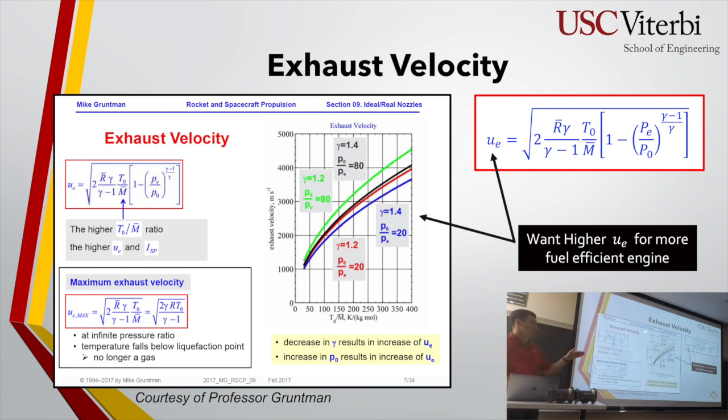And the Mach number is pretty much 0. Are you talking about macro velocity or thermal velocity? I'm talking, okay, yeah. So your Mach number is essentially 0. That probably would have been a better way to explain it. That's saying you're going to bring your fluid to Mach number equal to 0. If you think about it, your Mach number is your velocity over the speed of sound, and your speed of sound is the square root of gamma R T. So if that T is really, really high, then that means that A is big. And if A is a lot bigger than U, which is the velocity, the Mach number is 0, right? You have really high chamber temperatures in there, so essentially your Mach number is going to be 0, or really close to it.